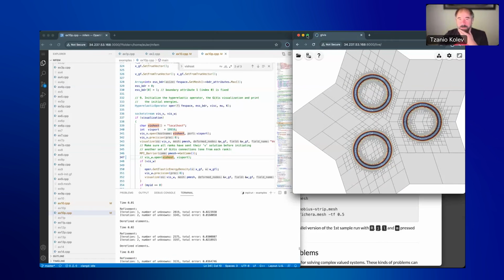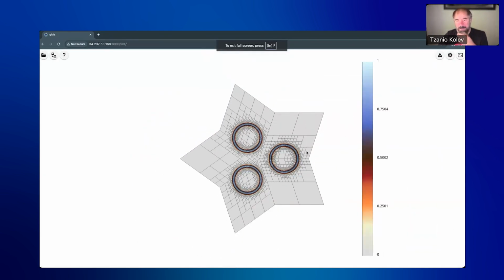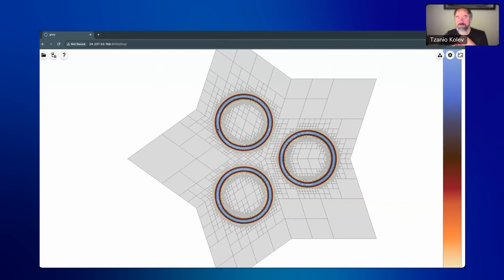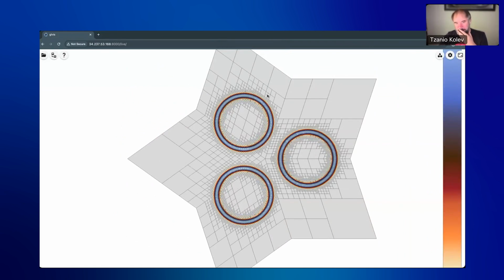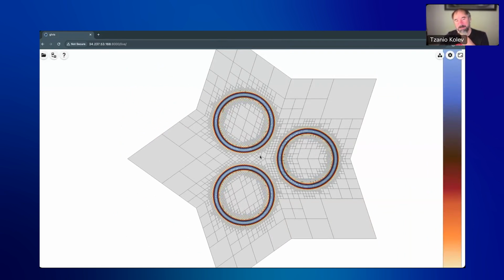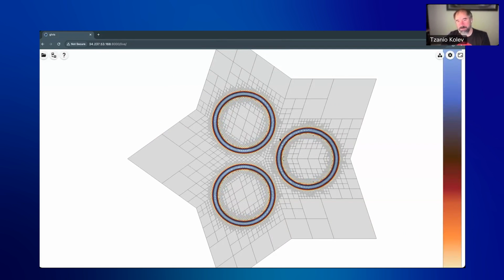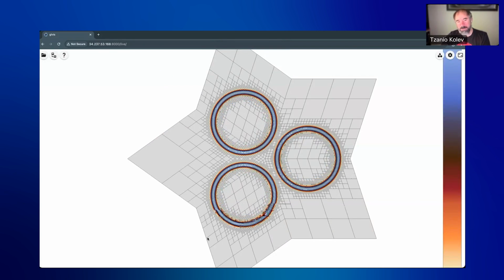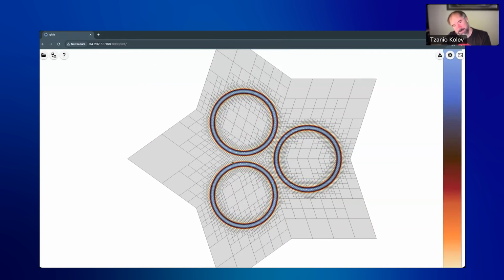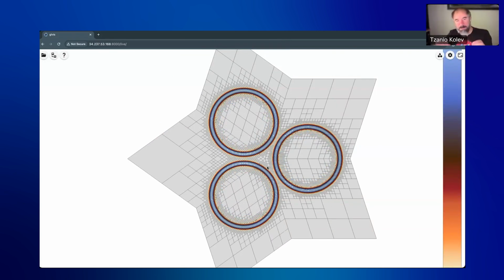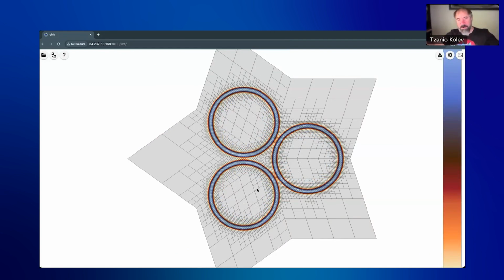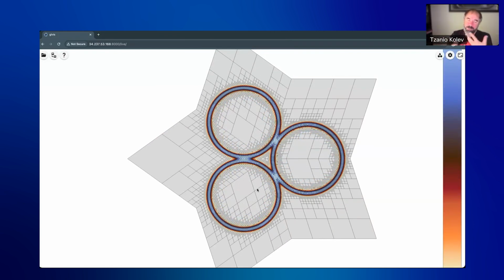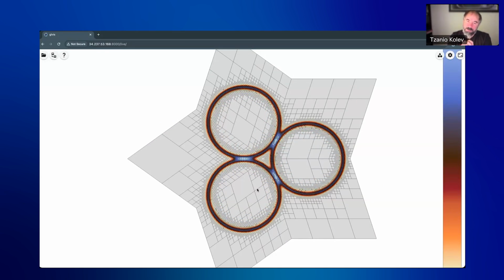and I put anti-aliasing. All right. So what happens here is we have these rings, and we refine and de-refine the mesh at the same time to resolve the rings. And basically you want big elements in the interior and outside, and you want small elements near the boundaries of the rings, and they grow. This is not an actual physics problem. This is a prescribed solution that evolves in time, and we're just testing this adaptive mesh refinement capabilities.